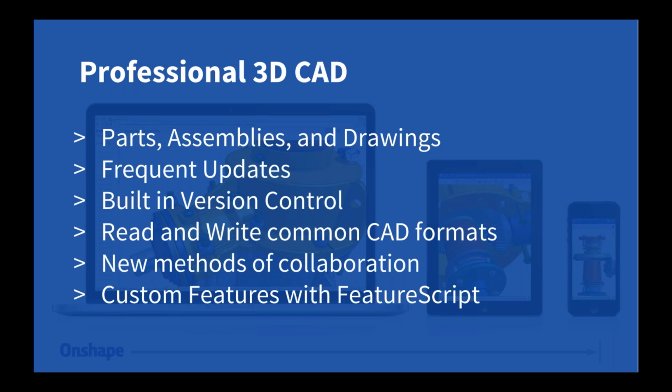So if you're using Onshape alongside another CAD application, or maybe you're working with a vendor, they'll be able to export in the format that they need. This includes STEP, IGES, Parasolid, DXF, the standards, but also native formats like SolidWorks, Inventor, Creo, CATIA. So there's a long list of supported formats, and it means that Onshape works well alongside other applications, and works well with that library of data you've built up.